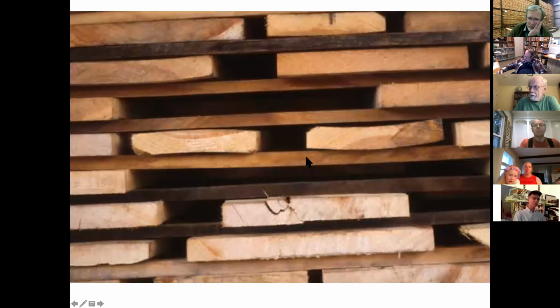And I apologize for the blurriness. I couldn't find my original picture that was as sharp. But you can see this is a stack of lumber that's drying from a dry kiln. This is a piece of yellow poplar. You can tell that this is the heartwood. So you can tell the pith was down here. You can see the growth rings right here. And so you can see from this piece that there's more tangential plane of reference on the top than there is on the bottom, kind of like my diagram. Not quite as drastic as my diagram. And so as the wood dried, it was able to shrink more on the top, and so you end up with cup. All right, now you might say, Dr.